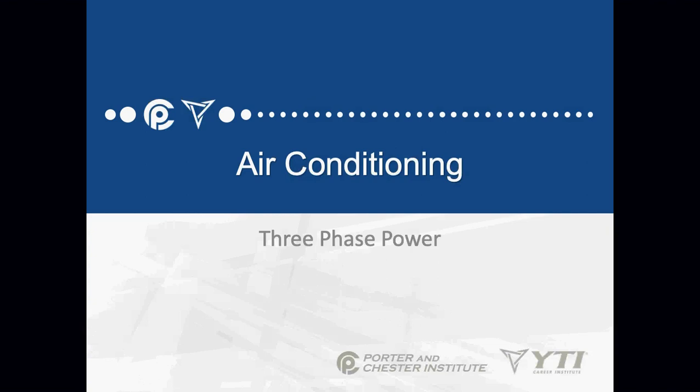Anybody else? Do three-phase motors have capacitors? No, they do not. Because we have three live, out-of-phase leads coming into three-phase motors. So three-phase motors do not need capacitors.